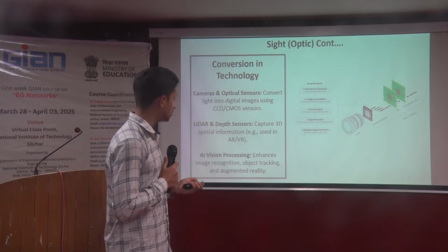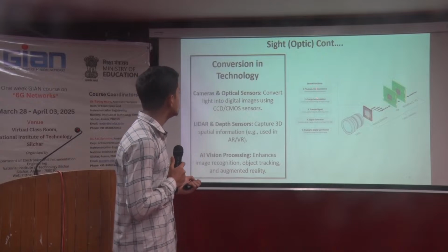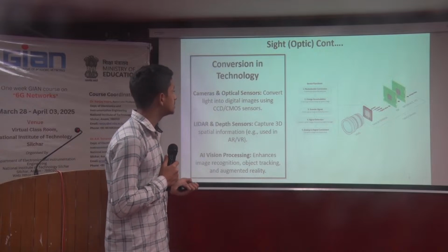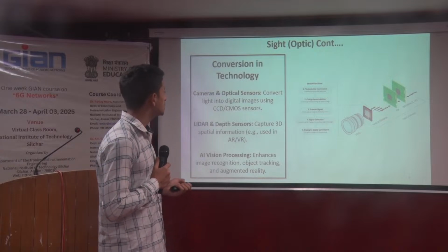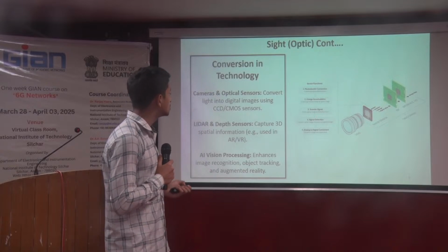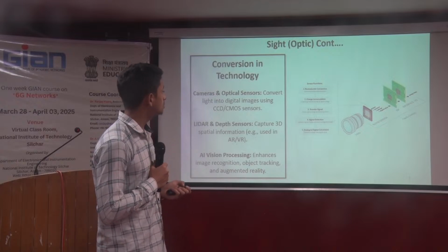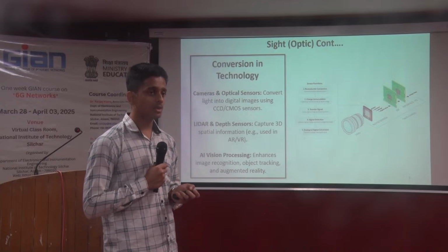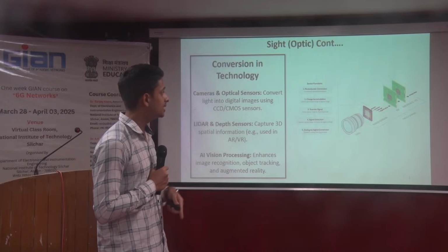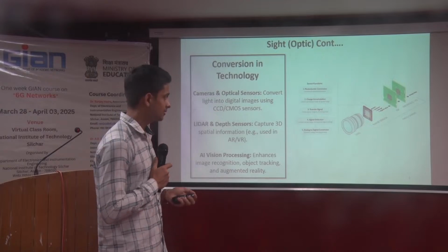And here is how it works, the sensor functions. First of all, the photoelectric conversion happens, and then the charge accumulation. The charge accumulation is done in the image sensor, and then it is transported to the ISP. There the transfer signal moves the charge to the detection node, and then the signal detection happens. For the analog to digital conversion, the ADC is used. The ADC's basic function is to convert the analog signal to a digital signal and store it, for basic human perception and image data conversion.